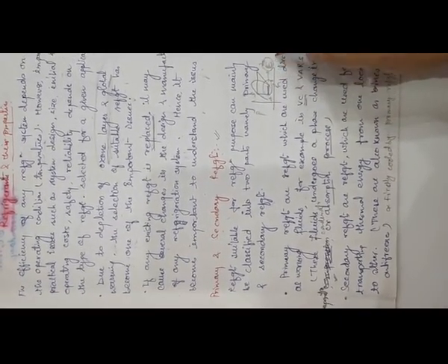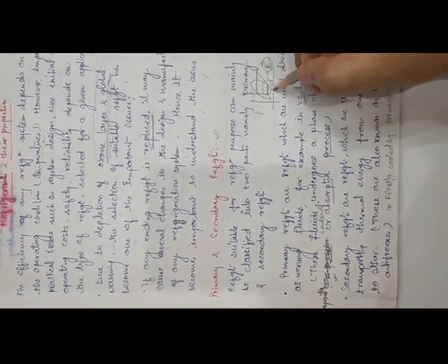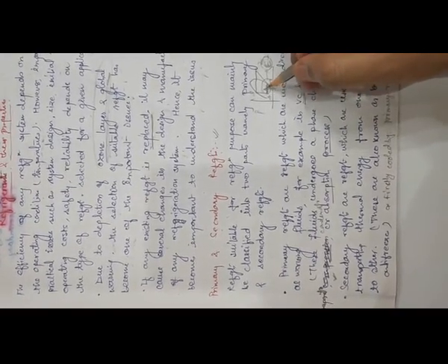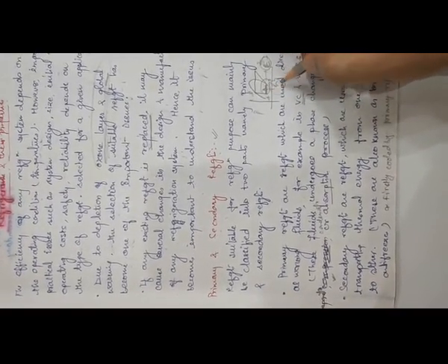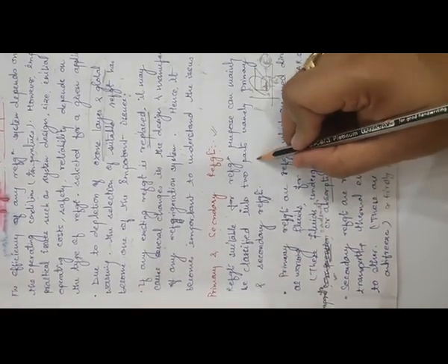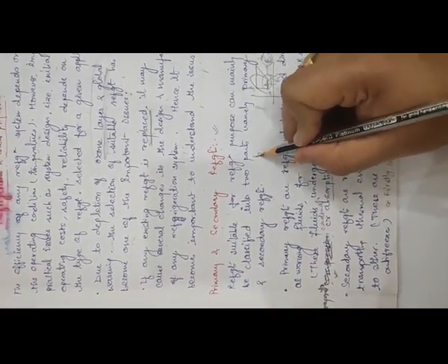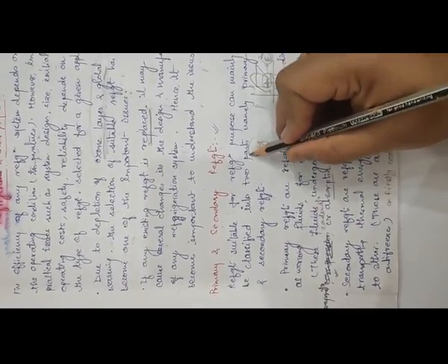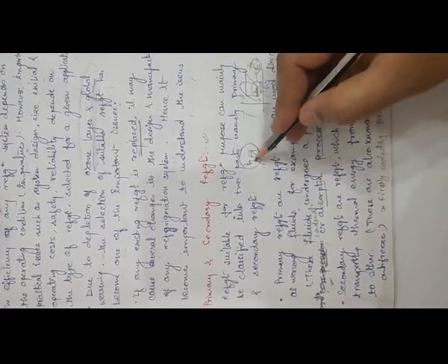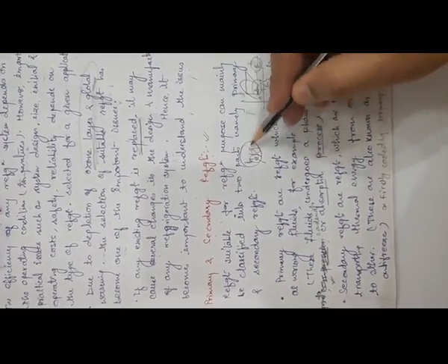This produces your refrigeration effect, because here the absorption of heat takes place from the confined space, and here your refrigerant changes its phase, which is represented by the latent heat of vaporization. When the liquid refrigerant comes into the evaporator, it uses this energy and changes its phase to the vapor phase. So primary refrigerants generally go with a change in phase.